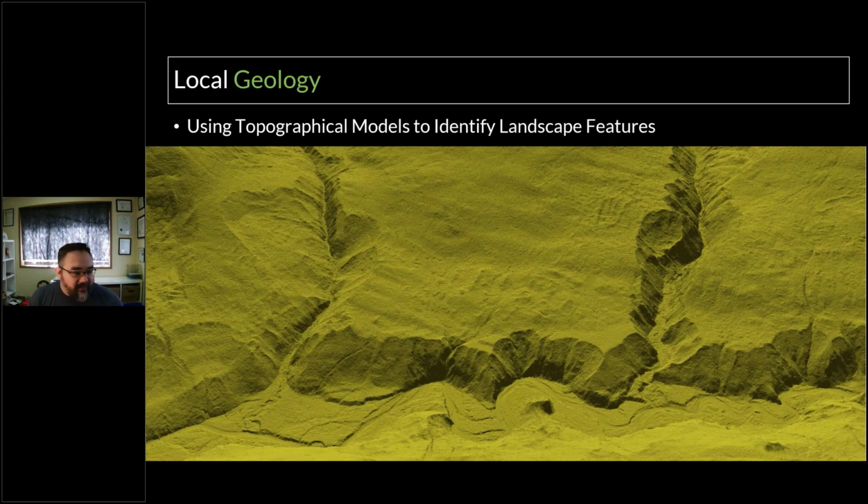As you can see on this one, I hope, at the top, or kind of mid top left hand side, you can see the outline of an old head wall of instability on, I guess would be the right bank of that gully. You might not be able to see that very clearly on the ground, but now we can identify those features up front. You can see down to the little scallops on the gully that's coming down on the right hand side. That's super clear in the LiDAR, but you might not see it on the ground.